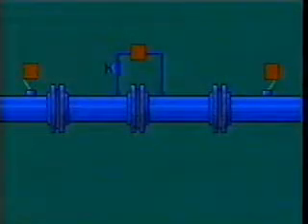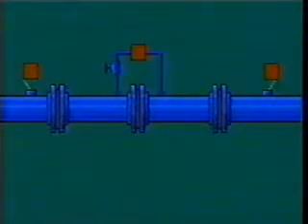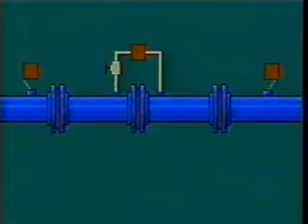Densitometers can be installed at several points on the meter run. However, the primary concern is that density is measured at flowing conditions, the same as those of the volume measurement. An insertion type densitometer can be located either up or downstream of the metering device. However, because its insertion creates turbulence, the densitometer should be placed some distance from the meter. All piping for slipstream densitometers should be insulated to keep the temperature the same as that of the flowing stream.